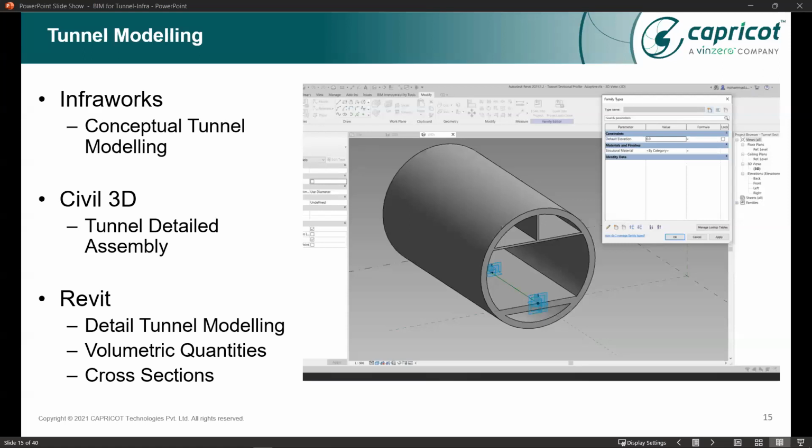Yes, it's visible. Okay. So like Abid mentioned, we transferred this data which we captured in InfraWorks, detailed that further in Civil 3D, and further we got those cross sections and redeveloped them in Revit. But to redevelop them, we actually used Dynamo to automate the process. So whatever data we captured in Civil 3D, or whatever data we detailed in Civil 3D, those cross sections are automatically created in Revit, and then further components were created out of those. The purpose for bringing this to Revit was, one part, documentation, like Abid discussed, and also to put up MEP services in it.